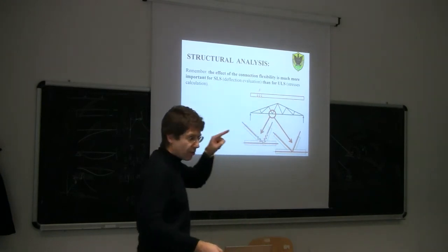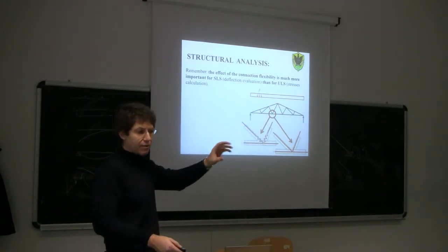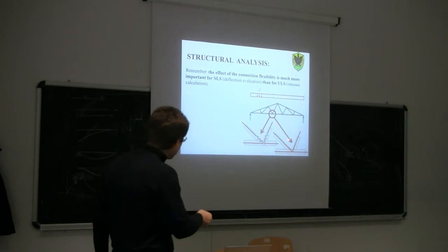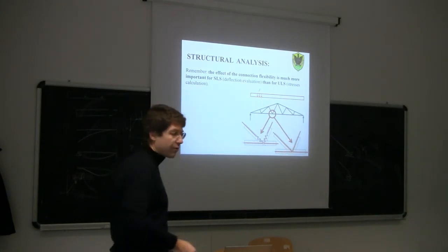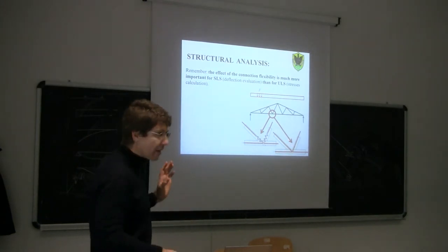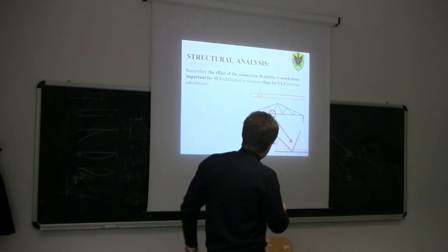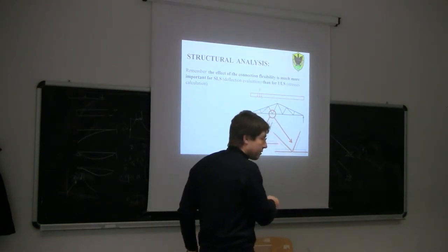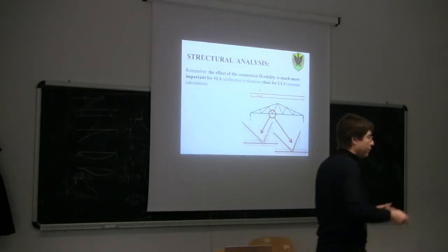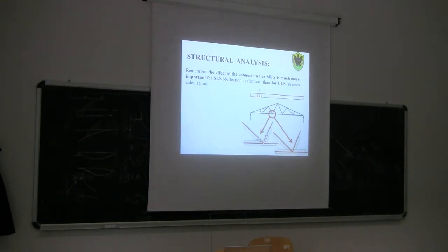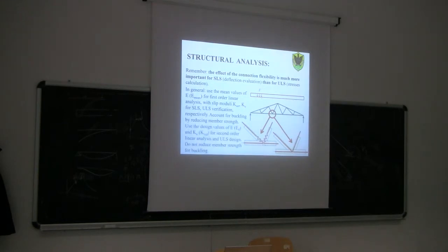You need to click on the joints and say end release for each member. So you need to release only the degree of freedom of rotation, okay? And then you should add, or you can also add this, the flexibility of this spring if you want with SAP2000. So it's not very difficult to do it using SAP2000. Okay, is that clear? Okay.